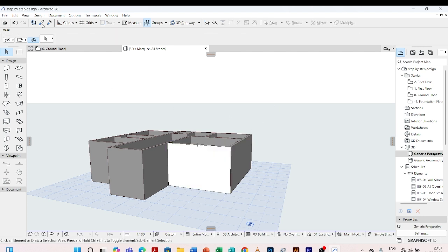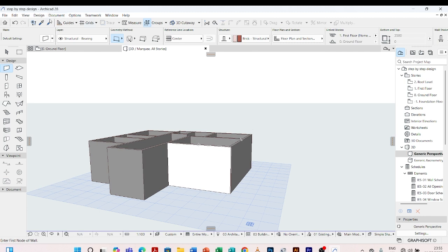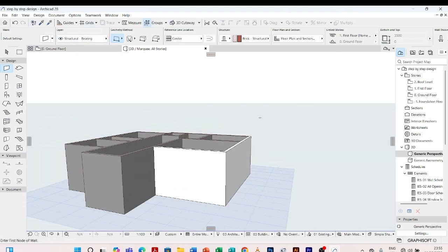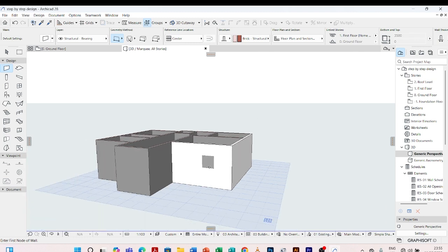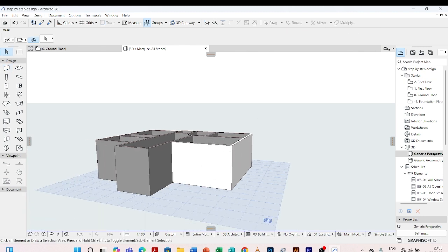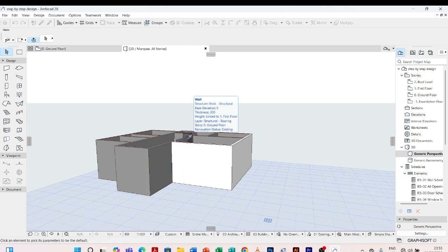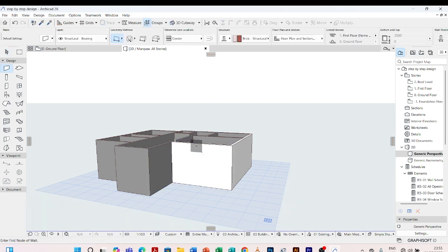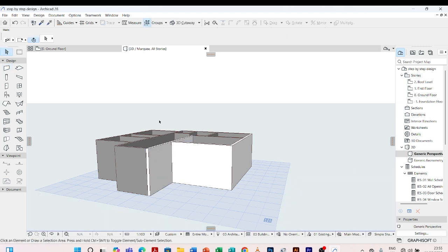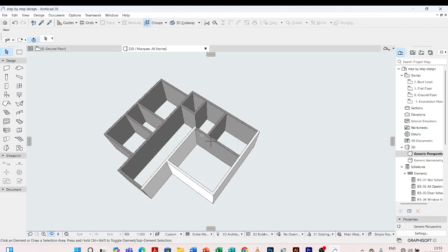So I want all my walls to be white. So you remember this pick and inject tool. You can either click on this, come and pick. Then I come here, I inject in that one to copy everything on this to this. The shortcut is Alt C. You come, you pick, then Control Alt C is to inject. Or in a similar way, let's first rotate, we can select these ones and change them at once.